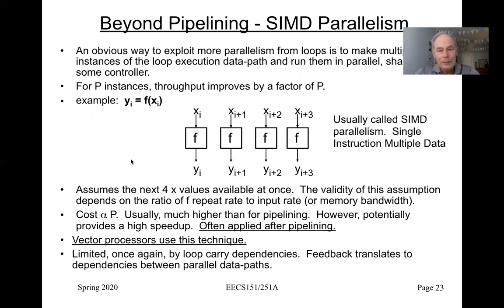Now, by the way, vector processors are SIMD units, like MMX or SSE, and AVX, I think it's called in Intel processors. These are the special vector instructions, and those get executed in a way similar to this. The vector add instruction adds a bunch of elements in parallel. So there's a bunch of adders that are all in parallel, and there's a big vector register that holds all the elements of the vector, and they go through all these adders.